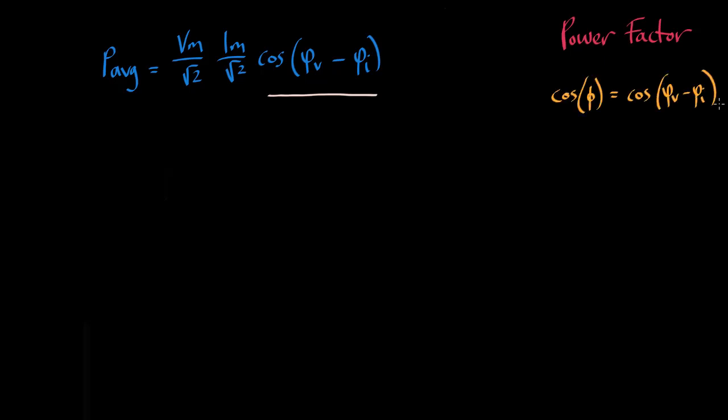The power factor will be the same whether the current is lagging or leading the voltage. Remember, cosines don't care about whether an angle is positive or negative. It returns the same result. Therefore, these terms are used to describe the circuit. Convention states that the power factor is taken positive when the current lags the voltage.